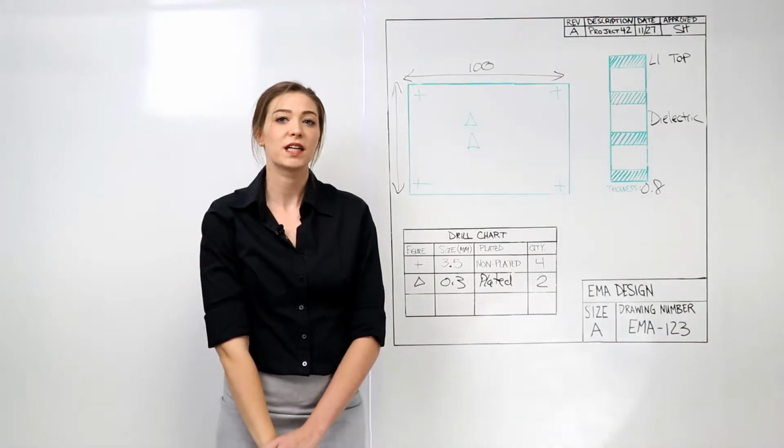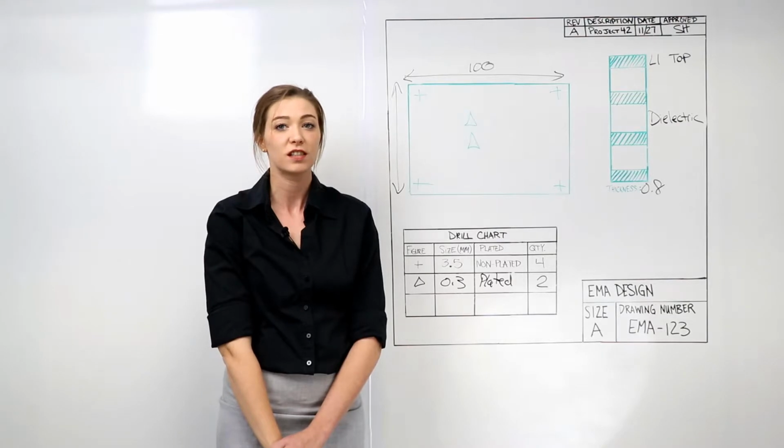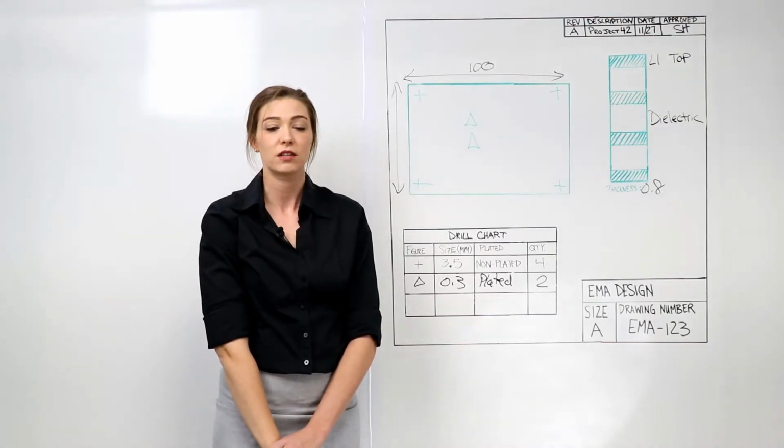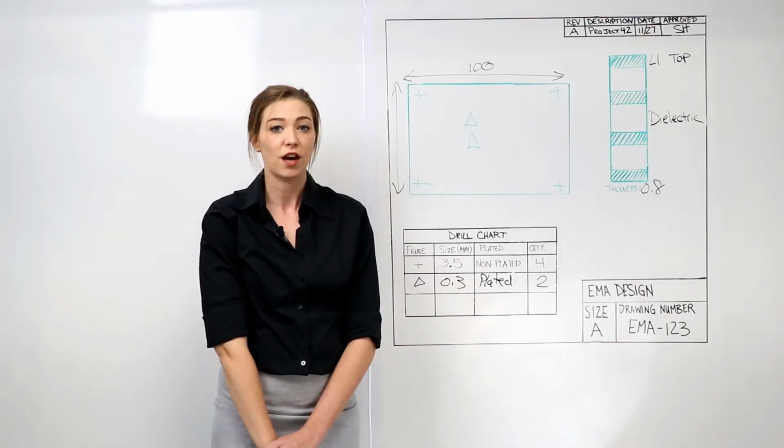If your design is impedance controlled, create a stackup that allows the manufacturer to vary the dielectric constant, trace width, and spacing to achieve the desired impedance. This will be discussed in depth in another video.